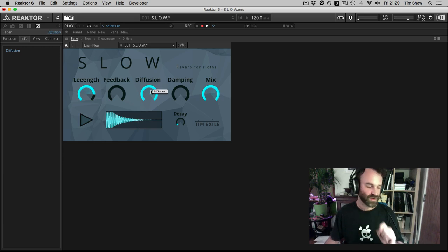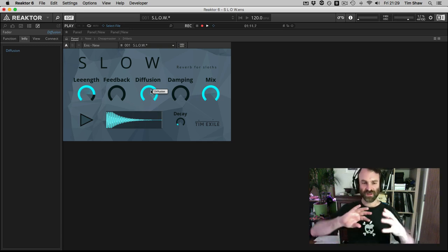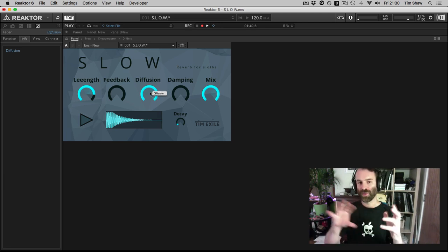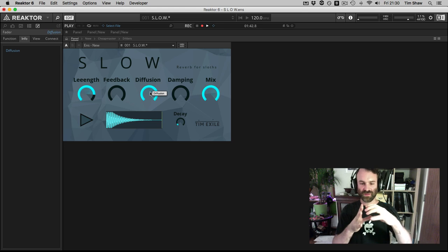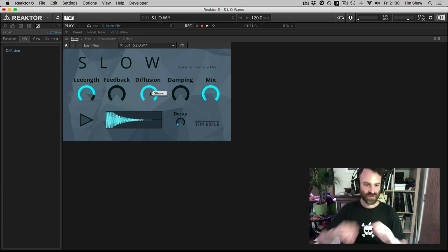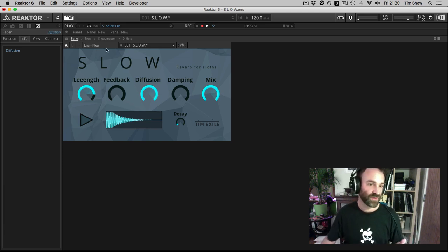it's basically just a very short delay line with lots of feedback. So you're just bringing up the feedback on that delay line. And it's diffusing the energy of that single impulse. And basically when you put a whole bunch of those together with well thought out differences in the delay time, if you like, then you get this huge reverb diffusion effect, basically. And that's how reverb works, pretty much.